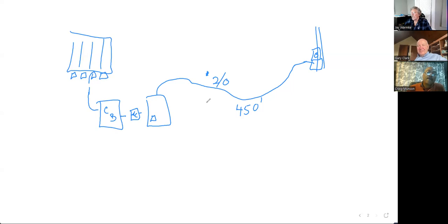trench. And that turned out to be a problem because we ended up pulling the wire all the way down the length. And then we had to take the conduit and feed it over each one section at a time from the end and run it all the way back the 450 feet. So we take a section and we feed it here and then walk it all the way down here to here, then take another section and walk it all the way down to here, and did that the whole way 10 foot at a time.